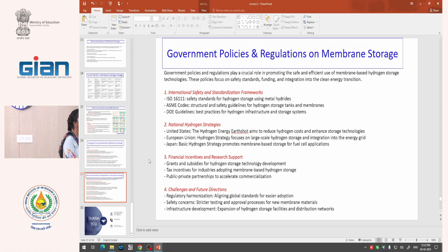If you are trying to keep the temperature constant but still want to switch between cycles, then you have to use different materials mostly. So temperature is very sensitive for the hydrogen absorption and desorption cycle, or otherwise pressure. Yes, pressure has an effect. You can switch between low pressure operation and high pressure operation to switch between cycles of absorption and desorption also. But if you change the material, then obviously you can have absorption and desorption as two separate systems in a cyclic process.